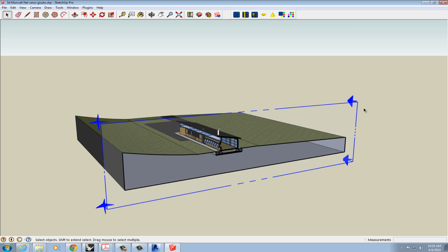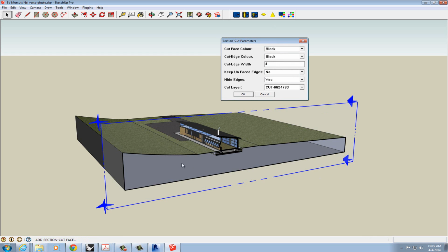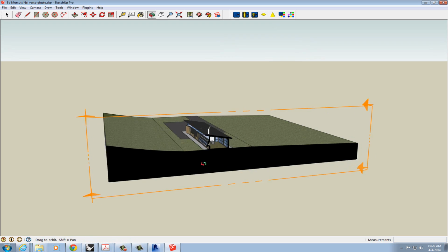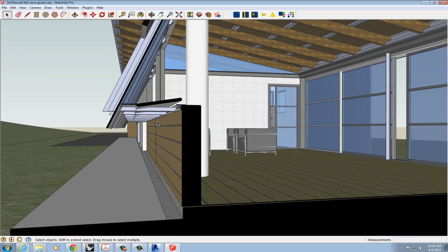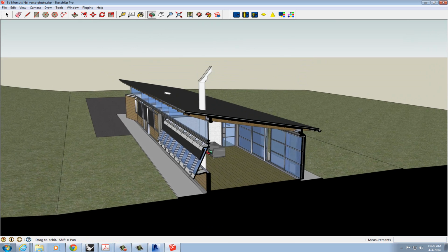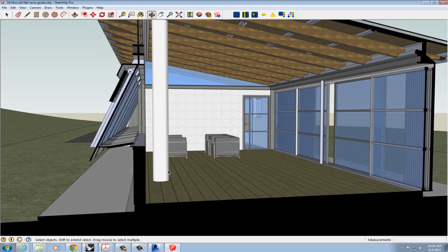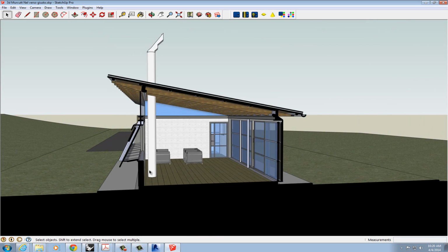So it's done, and then for the second stage, what I'm gonna do is again make it blue, and then add section cut face. What that's gonna do is create the section surfaces all across wherever the line cuts through it. It's very easy, very efficient, and you can do it for any type of drawings. The only thing is that you have to be very careful. It has to be airtight. It cannot be open surfaces. It has to be closed solid pieces.